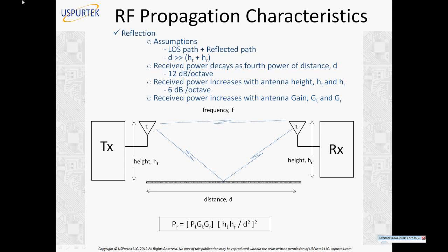So again, this is the equation, but let's go to the fourth power of distance. Well, if we have these assumptions, we have nothing in between. This is a very simple model. In this case, the fourth power distance will not change. But when we go to very complex scenarios where we have multiple reflections happening, as I told earlier, for example inside downtown with skyscrapers, there this fourth power might change actually. It may not be the same. It may be fifth power, sixth power, something like that. But in this simple scenario, it is fourth power.